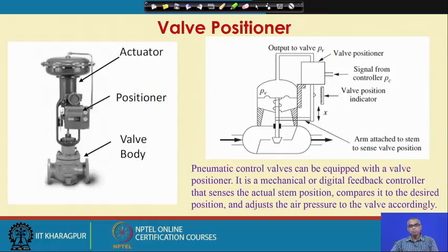Let us now talk about another important aspect of control valve, which is known as valve positioner. Pneumatic control valves can be equipped with a valve positioner. It is a mechanical or digital feedback controller that senses the actual stem position, compares it to the desired position and adjusts the air pressure on the top of the control valve accordingly.